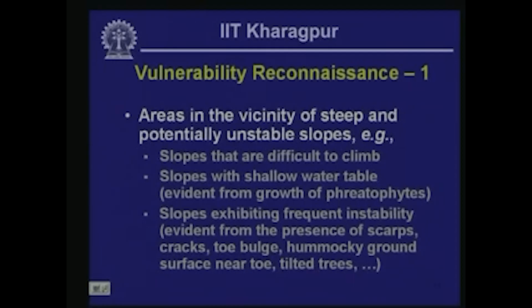There are several different plants that like to grow near the place where water is abundant, and they grow near the places where groundwater exits a slope face in many instances. So, their presence indicates the locations of potential landslide instability in that case.